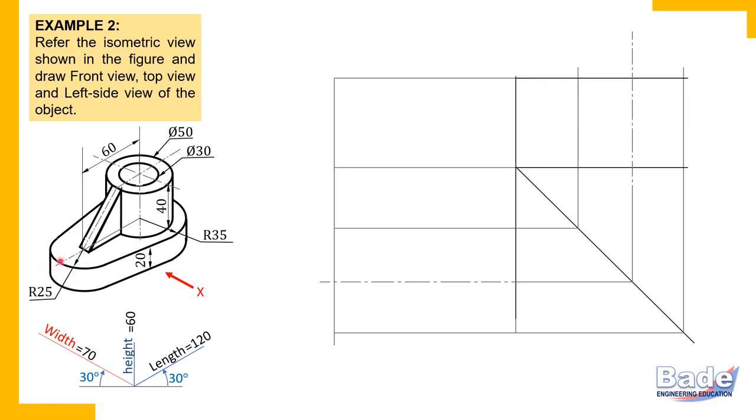Okay, now this is a curved edge. It has radius 25 and its center is on the axis of symmetry. On the axis of symmetry, this is the left end, this is the right end. From the left end, measure 25. Draw a center line, establish the center. So this is how we have located the center for this curved edge, and it has radius 25.